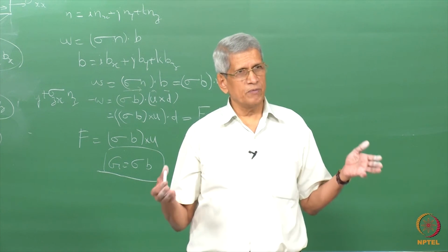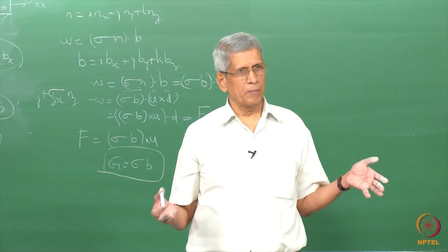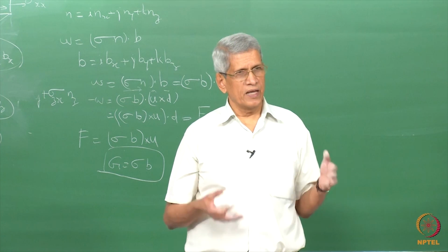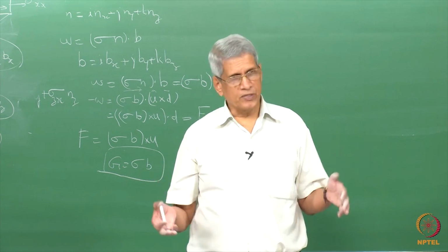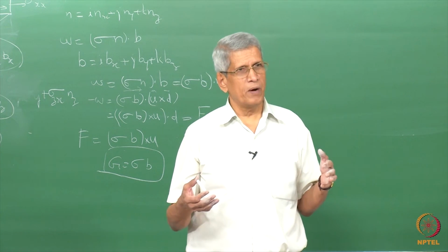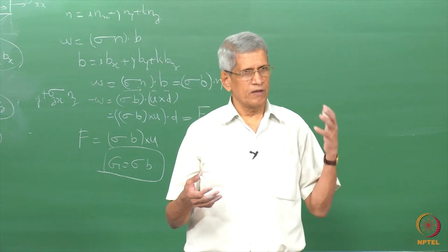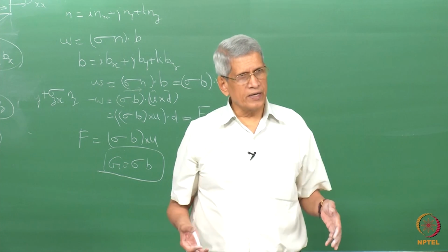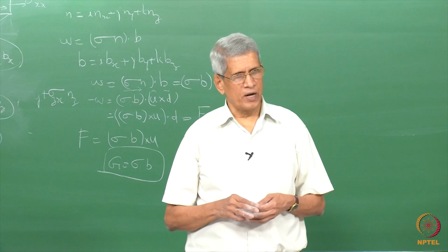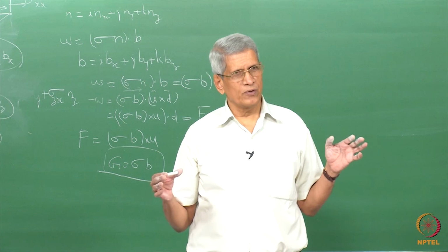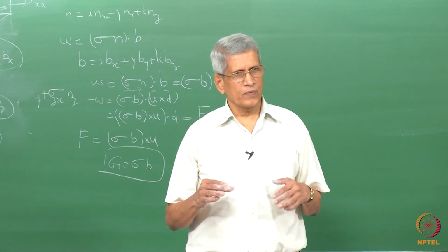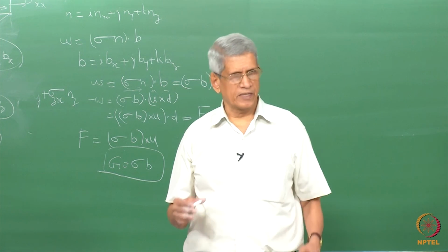This is exactly what we need to know when we deform a sample. A lot of dislocations are generated, and their interaction will lead to either a repulsive or an attractive force. Depending upon that, the response of the material will change. To understand how the material is going to respond, we should be able to find out the types of forces which act between dislocations. This we will take up in the next lecture.